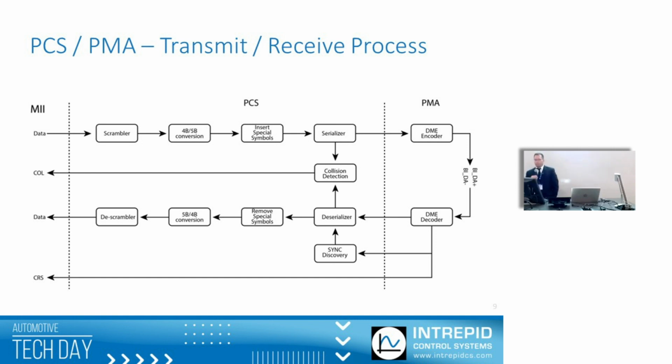So what happens is that 10BASE-T1S actually uses a very old technique, the CSMA/CD, the carrier sense collision detection. There are some legacy pins on an MII interface, collision detection and carrier sense, that are actually used for 10BASE-T1S. And this will tell the MAC, the media access controller, wait a minute, I can't take data right now, basically.